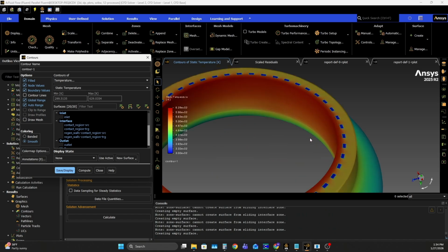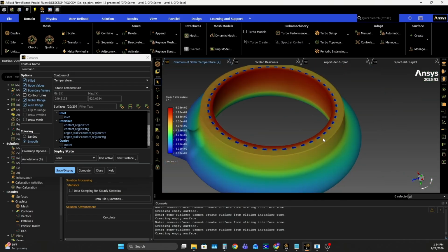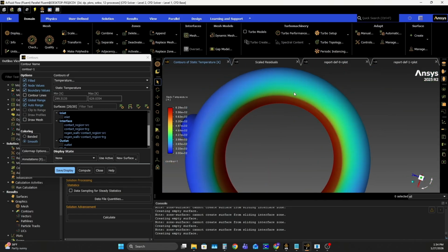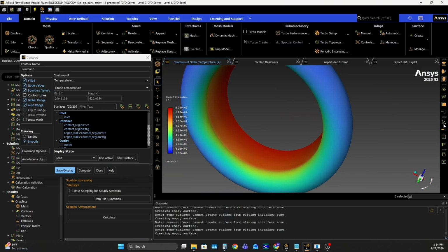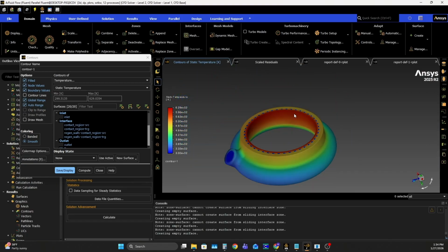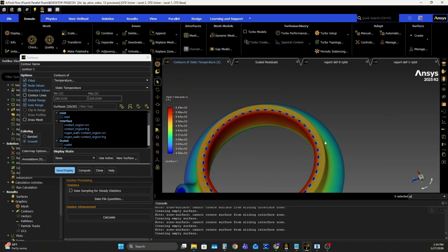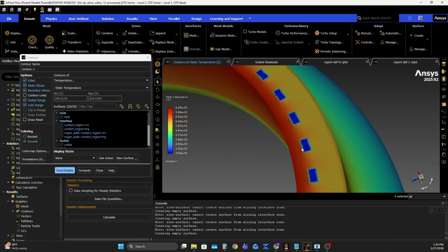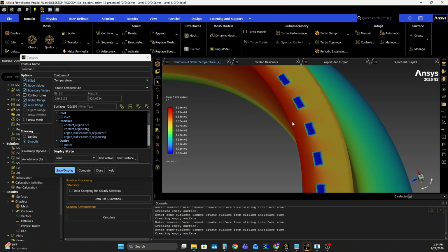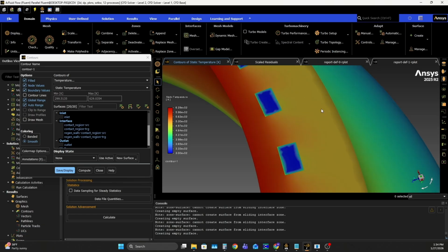Okay, so perfect. Now we can actually see what the temperature was over the entire bottom of the fuel annulus. We can see that our wall is hot here from our heat flux load, and then as the heat flux distributes out to the regen channels, it gets cooler and cooler. You can see, not a lot of heat flux makes it past the regen channels here.